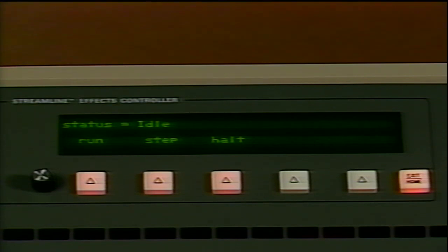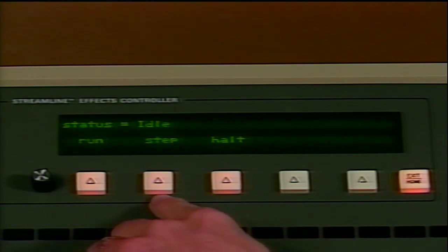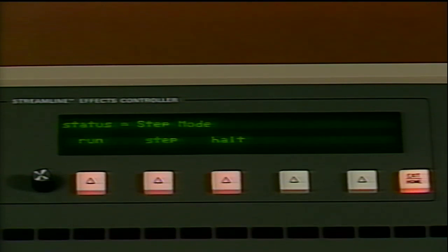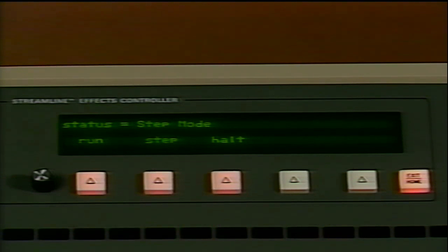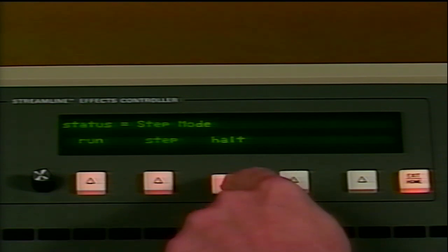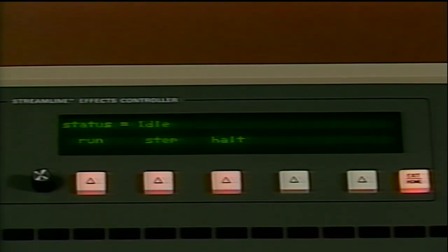Step is the next function in the Run mode display. Pressing Step the first time turns the step mode on. Pressing Step again performs the current event on the timeline. The timeline advances to the next field containing an event or events and waits there until the Step push button is pressed again. Step can also be canceled by pressing Halt or Last X clear. Note that holds require special attention when stepping through a timeline because an operator must manually perform a transition before proceeding.